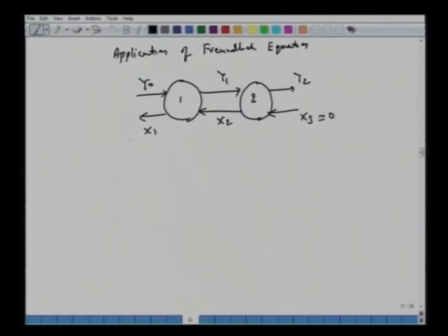The amount of adsorbent remains the same, SS, on a solid-free basis, and the amount of solvent is fixed, which is LS. Let's write down the expressions. Overall, we can make a balance: SS (x1 minus x3), which is 0, equals LS (y0 minus y2). Whatever is lost here is picked up by the solid as uptake.